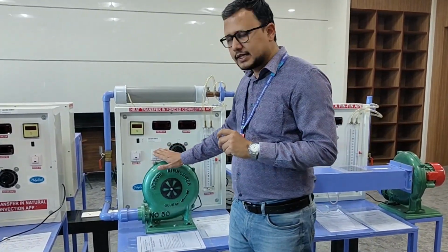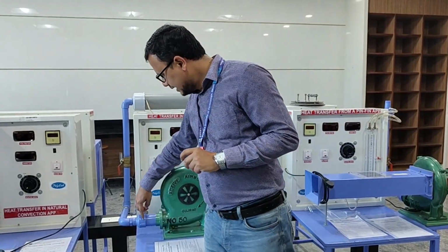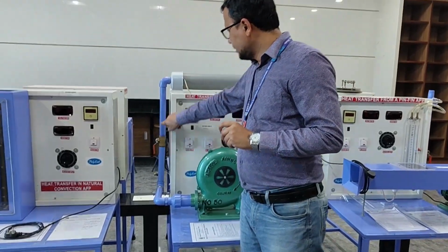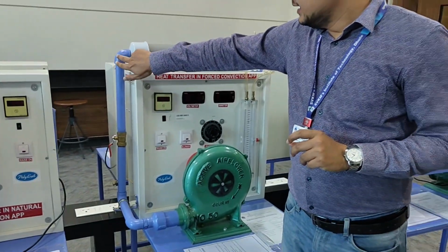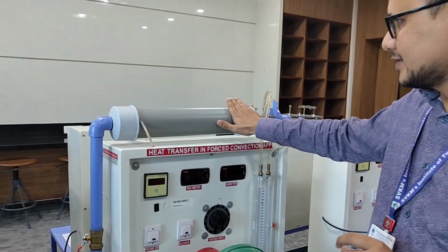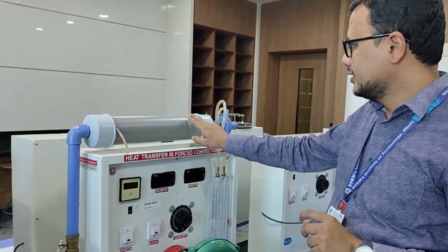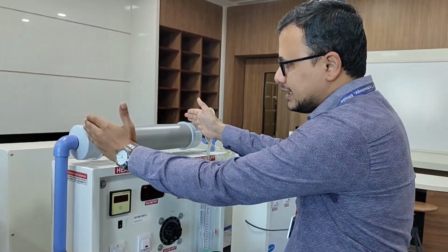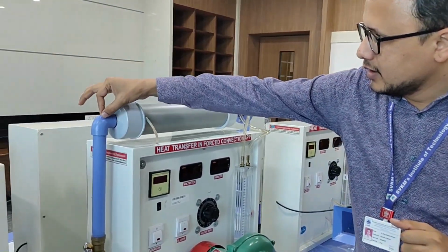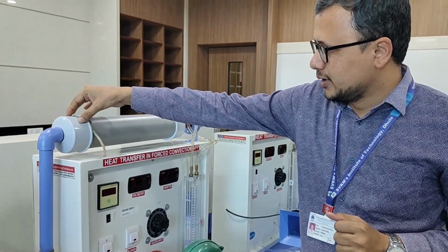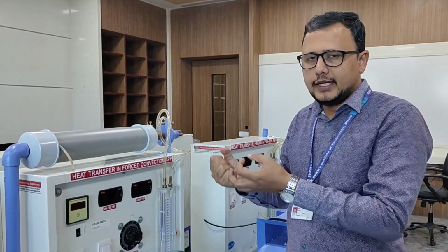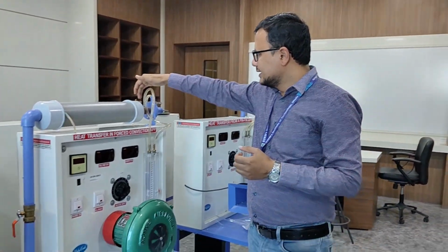So, once we start the blower, it will start circulating air through this pipe. We will be taking the reading of internal diameter of the pipe. From this end, the air will enter into this test section. Why are we calling this the test section? It is supplied with an electrical heater arrangement. So this particular part of the test section will be heated because of these electrical heaters. Cold air will enter into the test section at this point, and then it will come in contact with the heated surface. It will absorb the heat from the surface and it will exit on the other end.